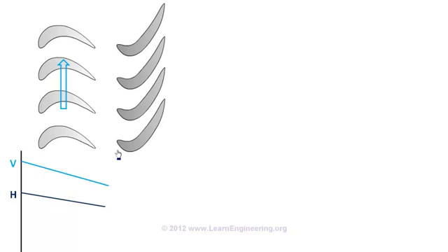Stators are also a set of blades, but these blades are stationary. They won't take part in the energy transfer. What they do is simply transform energy from one form to another. Or more precisely, they transform the enthalpy energy into kinetic energy. You can see the cross-section area of the nozzle decreases with flow, so due to its special shape the velocity increases. But at the same time enthalpy decreases. If you sum the change in enthalpy and kinetic energy, there won't be any change.